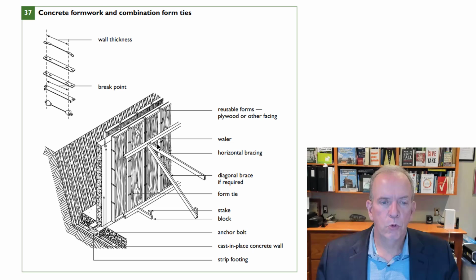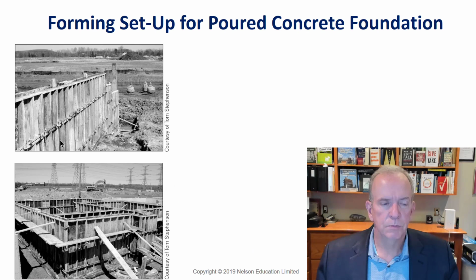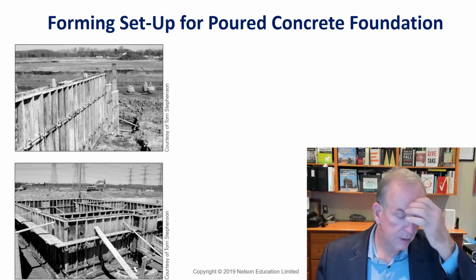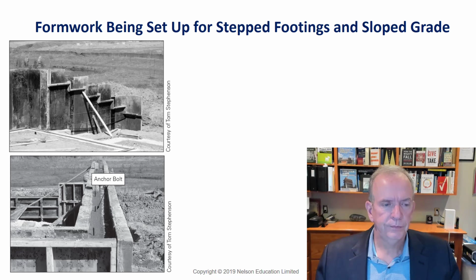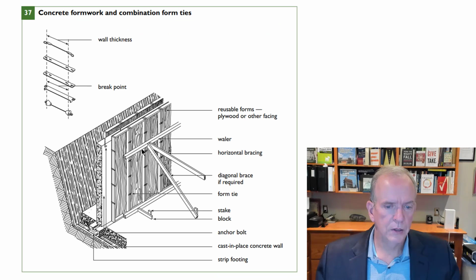And then you need a lot of supports, so the formwork will have some sort of support criteria, and they'll have wedges to tighten up the forms to the snap ties placed all the way around. Different forming systems work different ways, as I mentioned. They use a little bit smaller panel system than this now, because these panels were pretty heavy to move around. So there's always different innovations coming around with forming systems, but they pretty much all work on the same sort of criteria. Even in commercial work, they have some sort of snap tie system that holds them at the right spacing. And these components like the whaler, your horizontal bracing, and ties hold things in place.